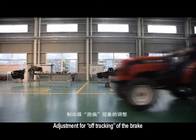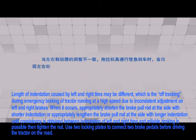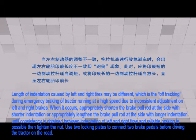Adjustment for off-tracking of the brake. Length of indentation caused by left and right tires may be different, which is the off-tracking during emergency braking of tractor running at a high speed due to inconsistent adjustment on left and right brakes. When it occurs, appropriately shorten the brake pull rod at the side with shorter indentation or appropriately lengthen the brake pull rod at the side with longer indentation until consistency is obtained between indentation of left and right tires and reliable braking is possible. Then tighten the nut.